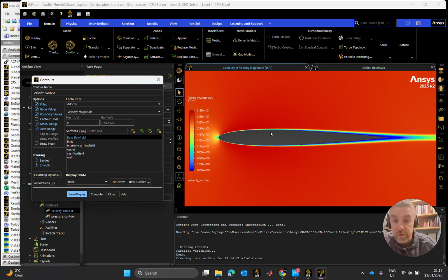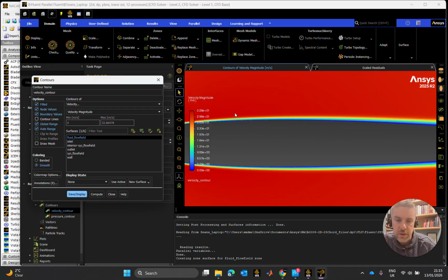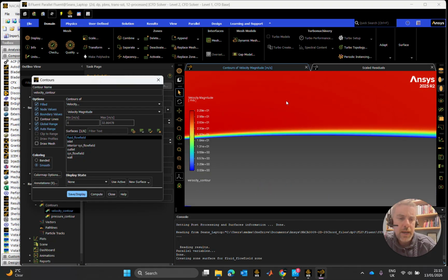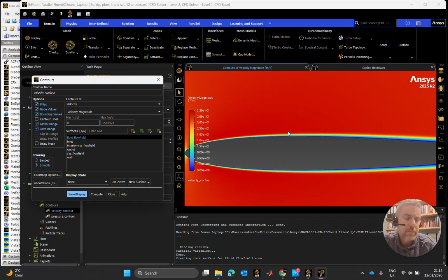I think it's widely enough accepted that the pressure differential across the top surface and lower surface of the airfoil does act on the airfoil surface, and it does lift the surface. Well, it doesn't really lift it. It allows the airfoil to be pushed from the high pressure into the low pressure region, and that does give an element of the lift.